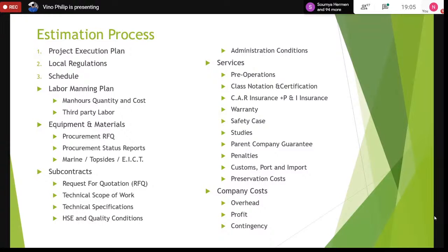The deck of the oil tanker is not very strong to support all the weight of the topside modules that are coming on top. So we have to create another plate. We have to create a web of structure, and we have to create a foundation deck that will support the whole topside. So that whole deck has to be refurbished as a foundation to support the modules above it. So that conversion is an expensive project, which is at the shipyard.